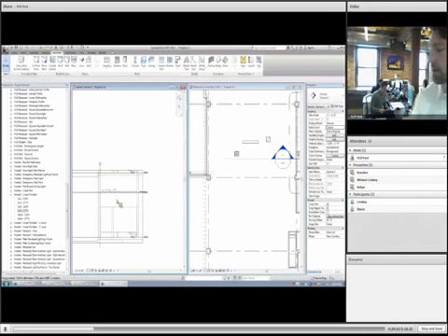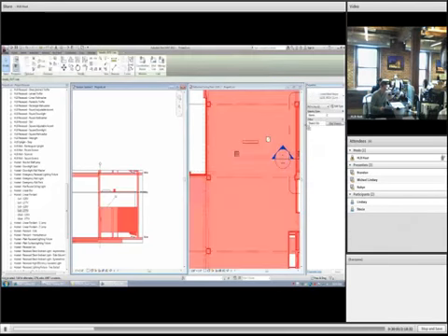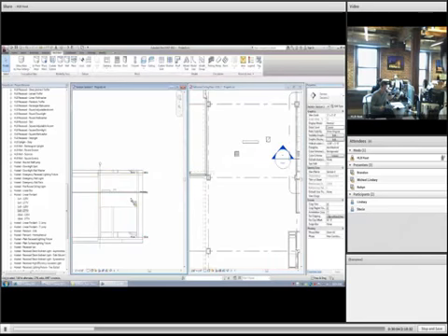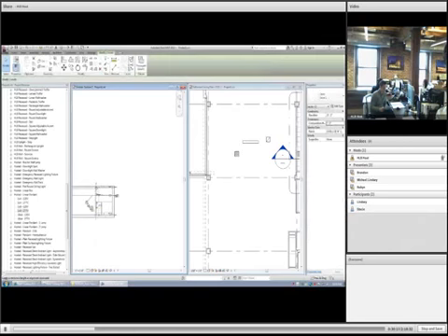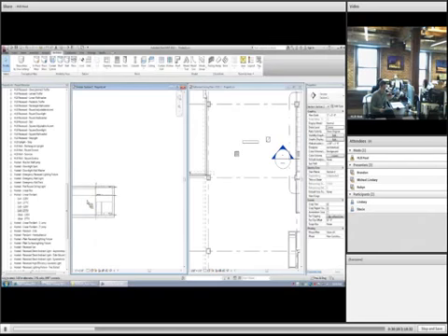It's a shared coordinate issue right there, because shared coordinates aren't set up properly in the file. Look at this. As soon as I took off the shared coordinates of that linked file, and you won't have this trouble normally, you can tab through, align, select the ceiling, select the level, and then lock them together. So as that ceiling goes up or down, your level moves as well.